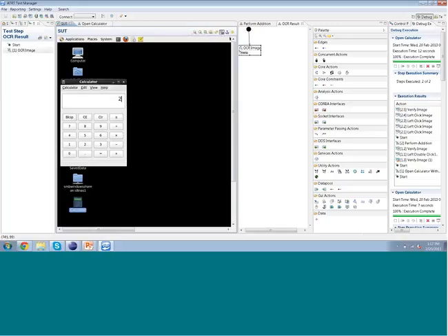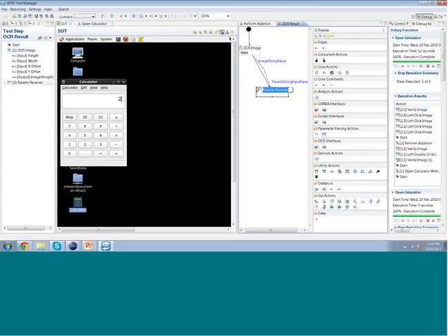And now that I have pulled that value in, I can do things with it using parameter edges. So you can see if I do a drop down on this OCR image on the left-hand list, it has an output of image string value. And what this means is that image that I'm OCRing and getting a value for, I can pass that into other tools within ATRT. So for example today, the one I'm going to pass it into is a parameter receiver action. And what this will do is this will pause my execution and show me that value. So I'm going to select that and place it on the canvas.